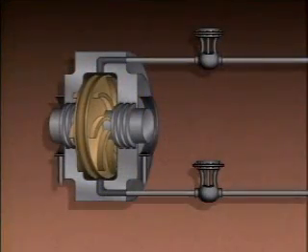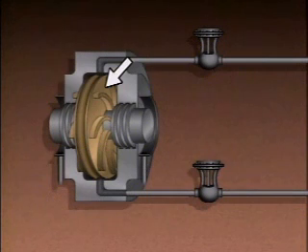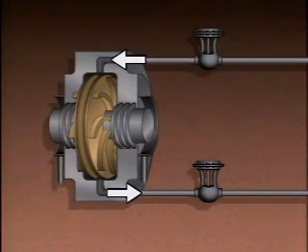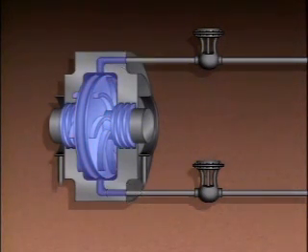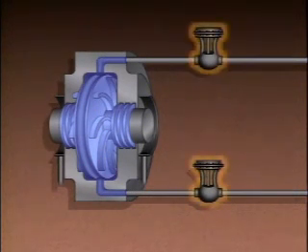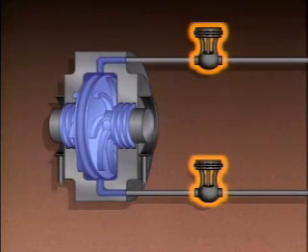A second alternative to steam seals is water seals. When water seals are used, water is pumped through a special gland to minimize leakage. A gland is a device used to create a seal. The advantage of water seals over carbon seals is that their parts tend to last longer. A typical water seal uses an impeller that's mounted on the shaft to circulate water through the gland. The circulating water fills the opening between the shaft and the casing, preventing leakage. Valves in the water supply and return lines maintain the proper water pressure in the gland.